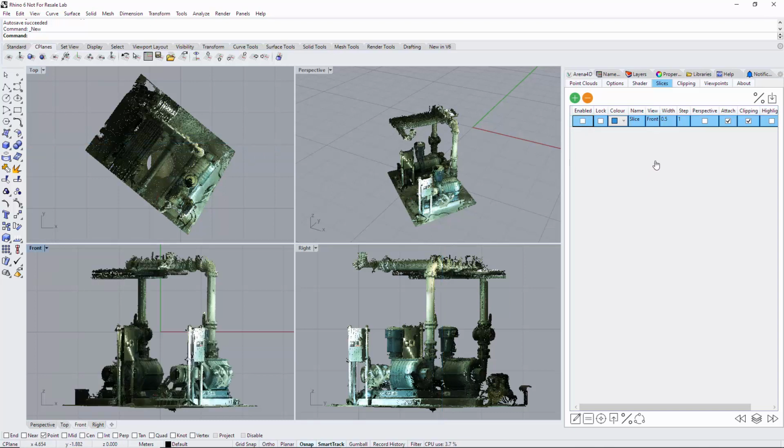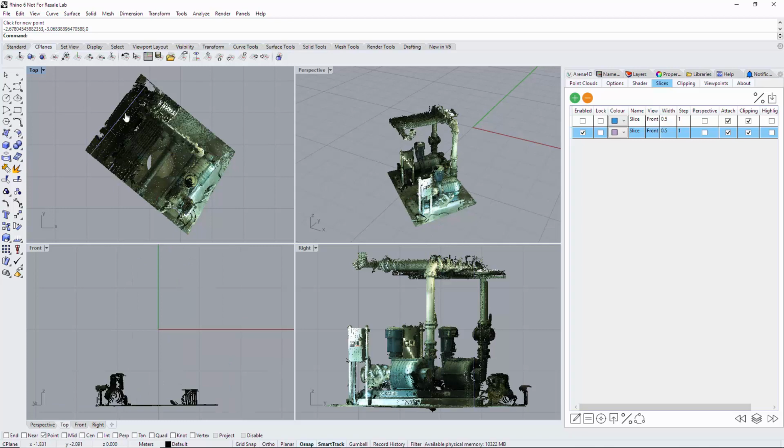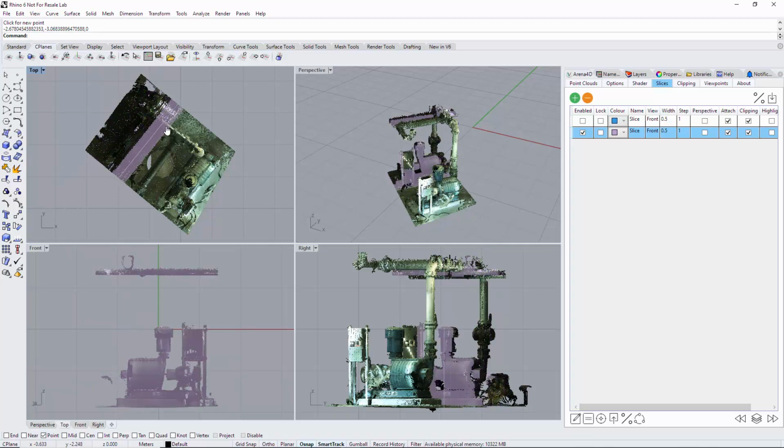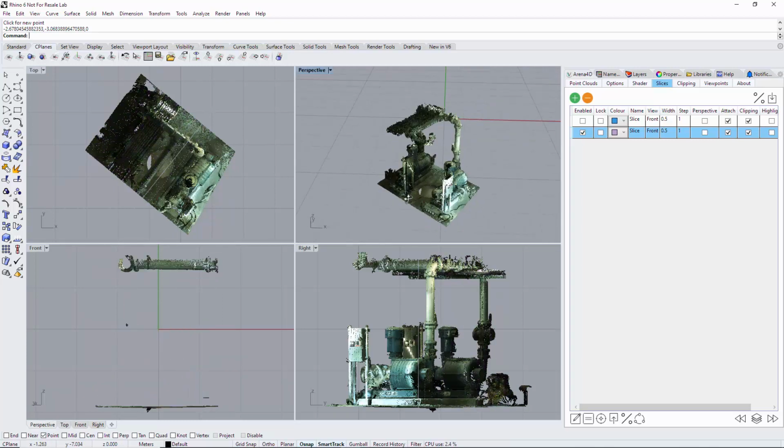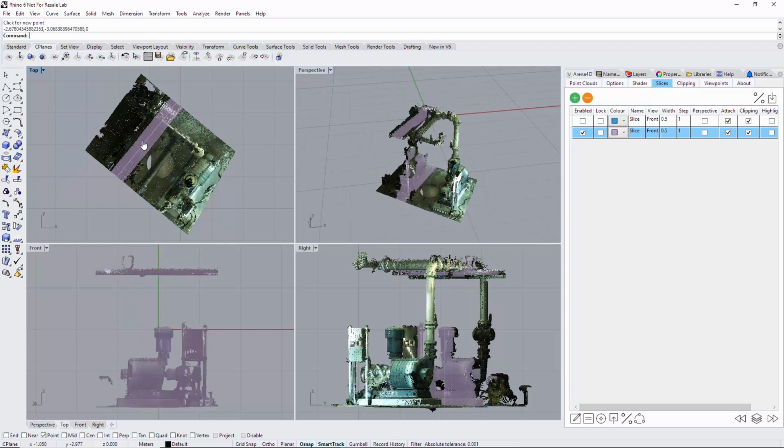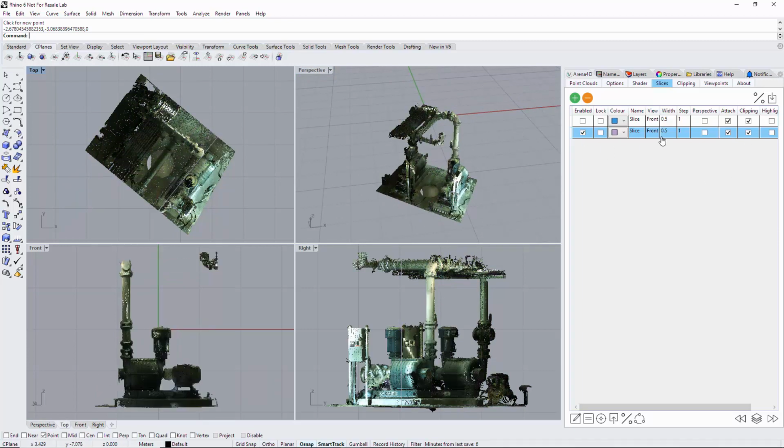off to declutter the screen, select 2-point slice, and I'm going to draw on the data. I get 2 points to add, and there's a line to show us, and there we are. Now that's moved that slice perfectly with our data. The slice is a normal slice, so you can perform all the operations that you may have seen in previous videos.